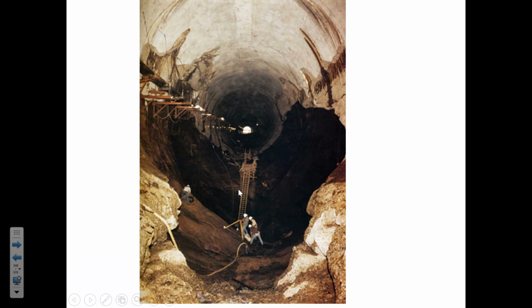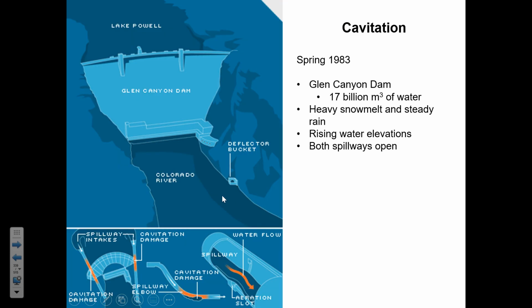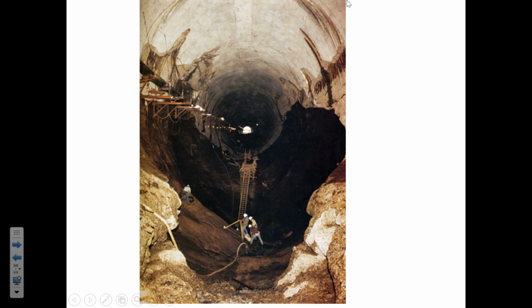So fortunately, they were able to repair this and to prevent further instances where there's the damage of water that's flowing at very high velocity, low pressure, where cavitation occurs. They now have the ability to inject a cushion of air so that the water isn't in contact with the concrete